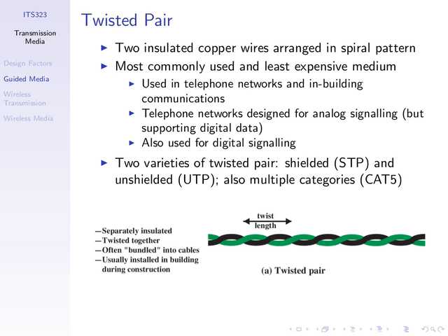Within them, there are different quality levels or different categories. So you'll hear about things like Category 5, Cat 5, Category 6. It even says on some of these, this is verified to Category 5. It says on here that this is a Category 5 wire. So it's to do with the quality of the wiring and the shielding, or the quality of the copper wires inside those twisted pairs. And I guess it's more expensive. And it's more expensive. The higher the quality, the more expensive the cable.